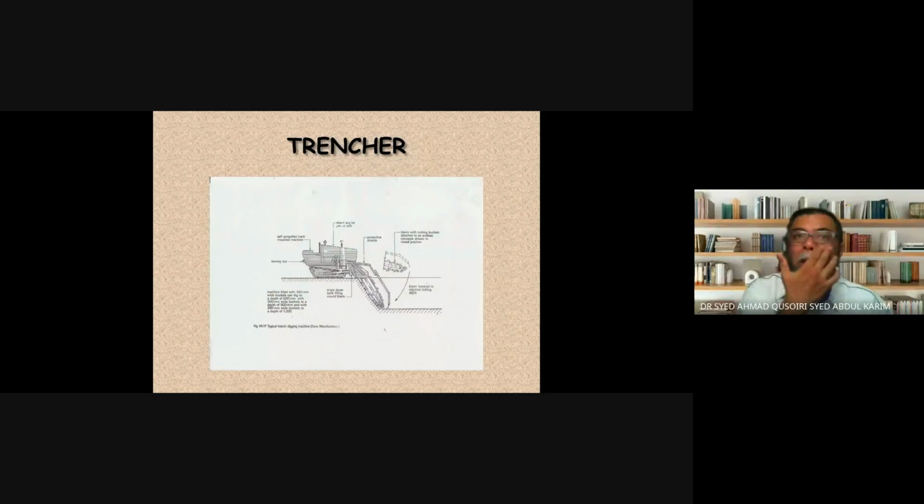And then this is a trenching machine, yeah? Trench digging machine. This type of machine we usually see for special jobs. If you have a job to build a very long drainage, or you need to put very long pipes into the ground, then it would justify the use of this trench digging machine, because it can really speed up your work.